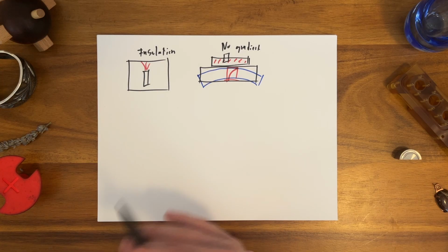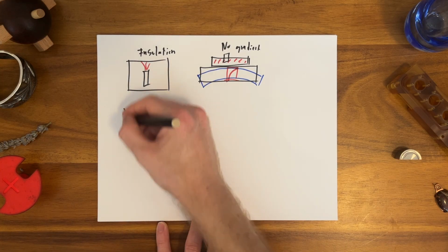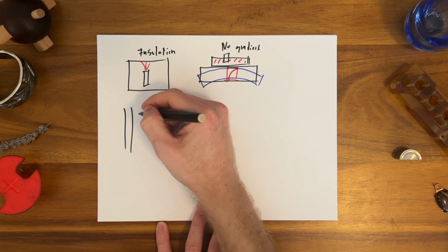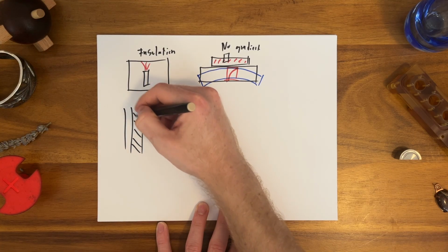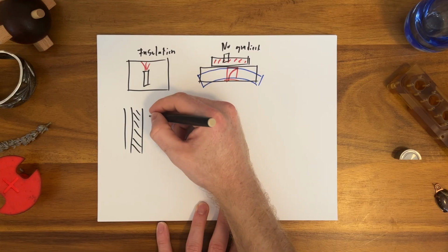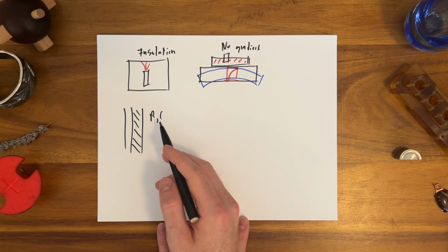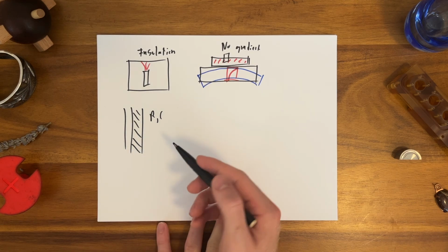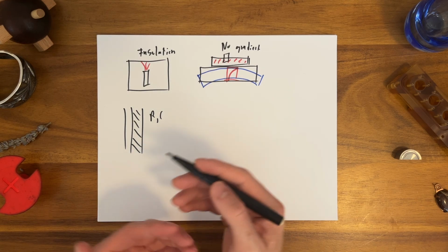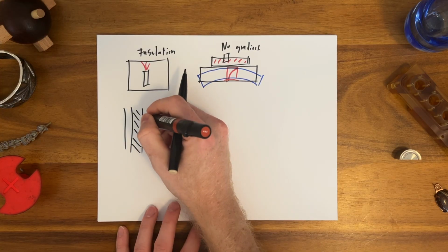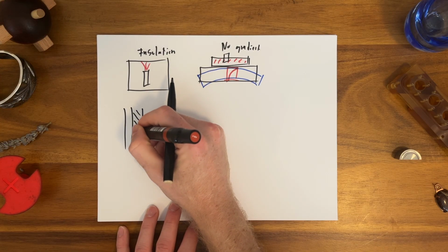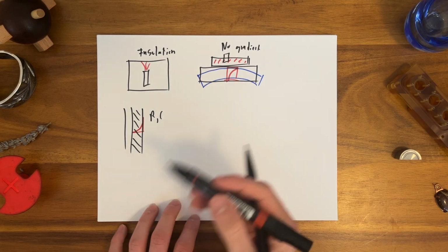Normally, your thermal tools would actually not be that useful here. If you start with a lumped parameter model, let's say you have your enclosure and an insulator in front of it, and you start trying to write R's and C's and time constants and heat capacities to make a lumped model for this, you're going to get the answer wrong, because you can't lump it when we're looking at really sharp temperature distributions in the material. This will capture average temperature only.